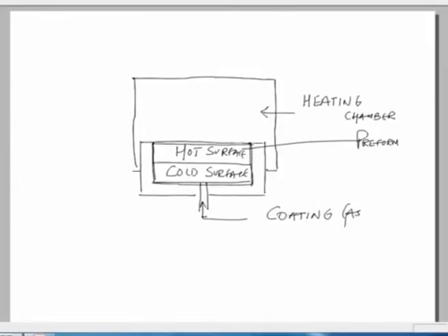Solid preform means that through this we have to pass our gases and we have to deposit the solid reaction products inside the preform so that the matrix is created. So the reinforcement has already been kept. This is basically a reinforcement, that is a preform. And this is, we can say, the exhaust gases.